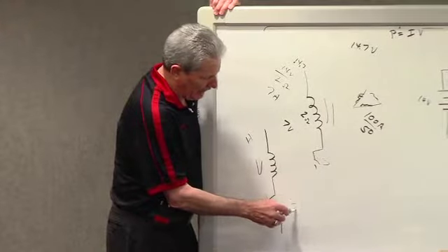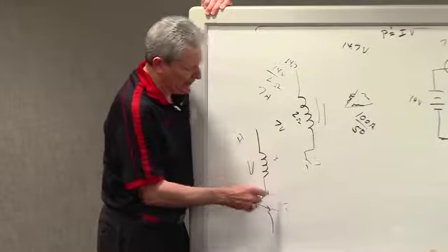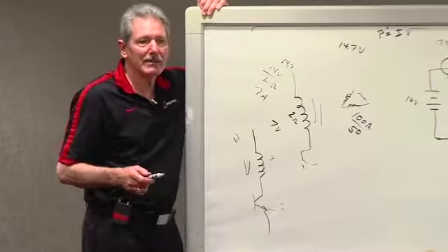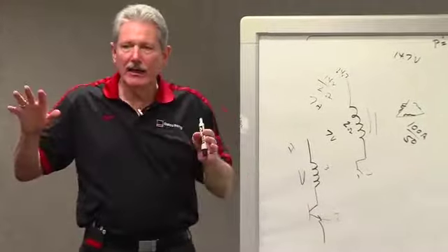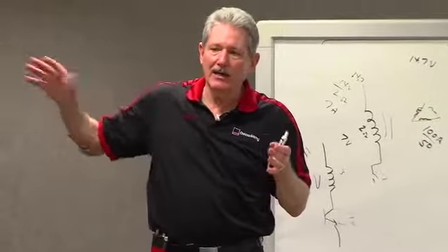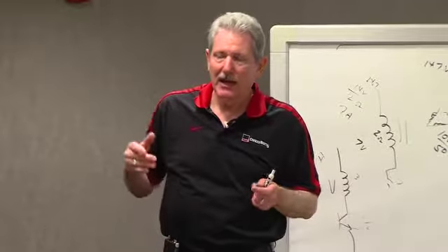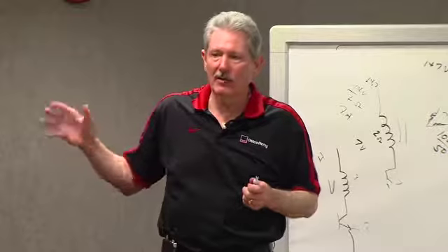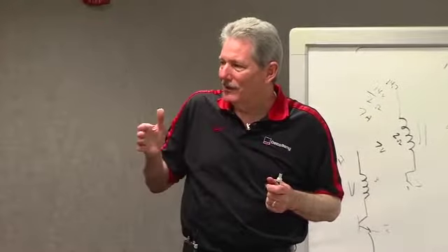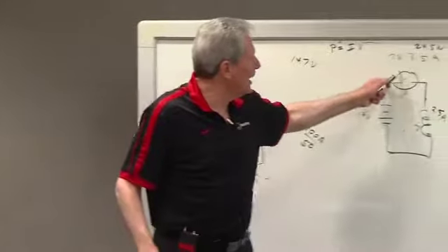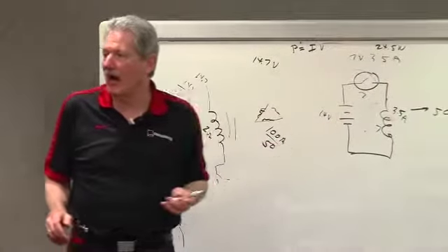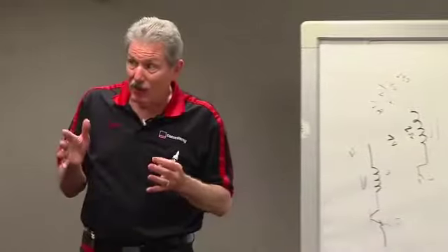If it's 0.1 volts and I've got 3 amps, that's 0.3 watts. So the reason why you switch regulators, any power supply that you've got uses a switching regulator. High performance audio equipment that has a high output power generally uses switching because it's more efficient. You don't burn up that energy, burn up that power. So that's why our regulators switch.